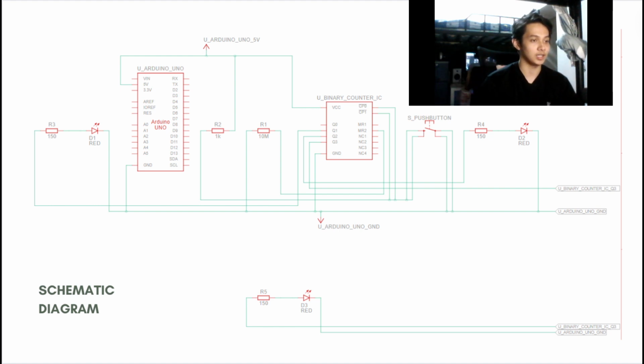the counter IC. So moving on to the counter IC, we know that VCC is connected to the power source, and then CP0 and CP1 are what handle the inputs that it will receive from the breadboard or the circuit. In our case, we use a push button in our project. Whenever the push button is pressed, it will be received by CP0 and CP1, and then it will iterate the count by 1, 2, and 3, depending on which is connected to the Q